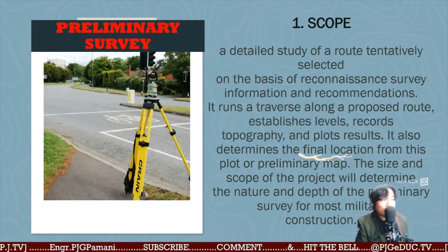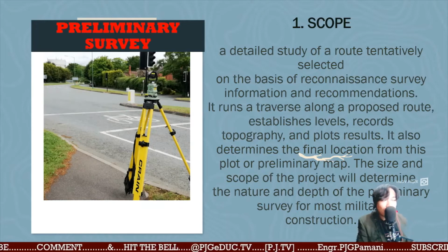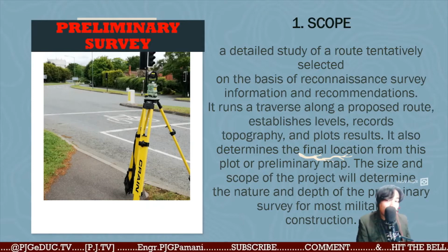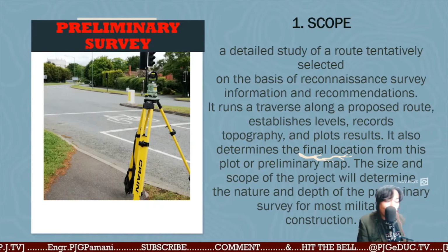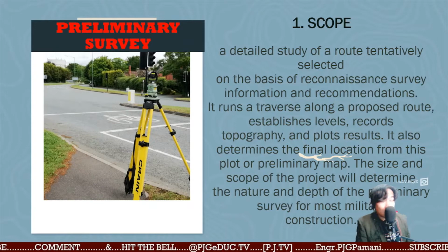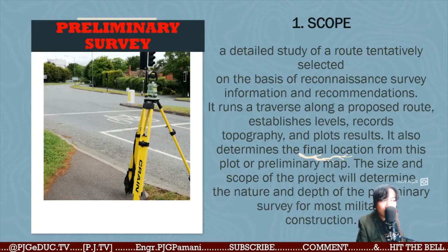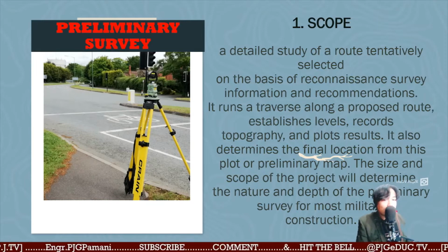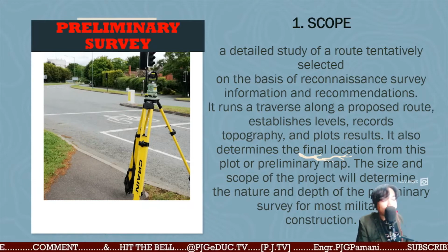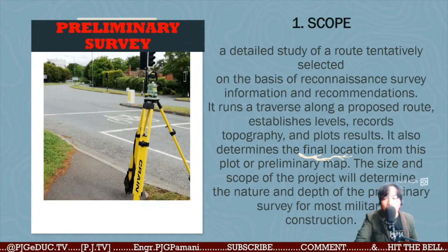Then it runs a traverse along a proposed route, establishes levels, records topography, and plots. You will then start surveying methods that will analyze the raw information that we'll be needing later on for our roadway construction or roadway planning. It also determines the final location from this plot or preliminary map. The size and the scope of the project will be determined by this preliminary survey. The nature and depth of the preliminary survey for most military construction.